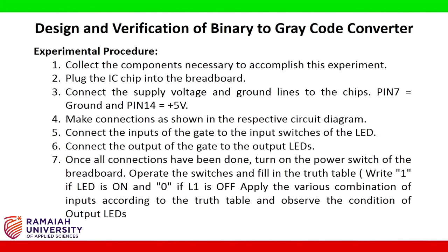Pin 7 is ground and pin 14 is plus 5 volt. Make connections as shown in the respective circuit diagram. Connect the inputs of the gate to the input switches. Connect the output of the gate to the output LEDs. Once all connections have been done, turn on the power switch of the breadboard.